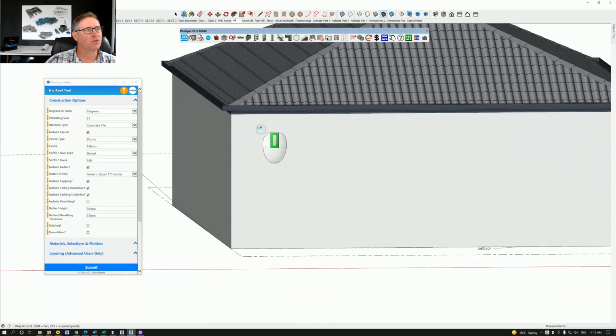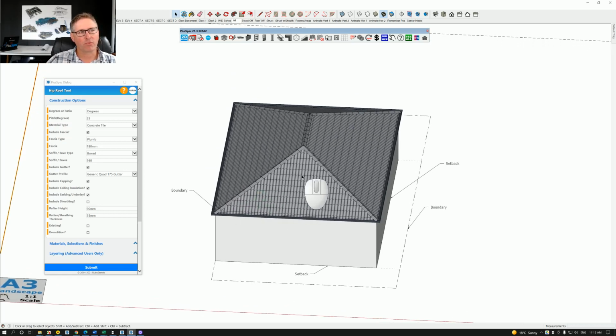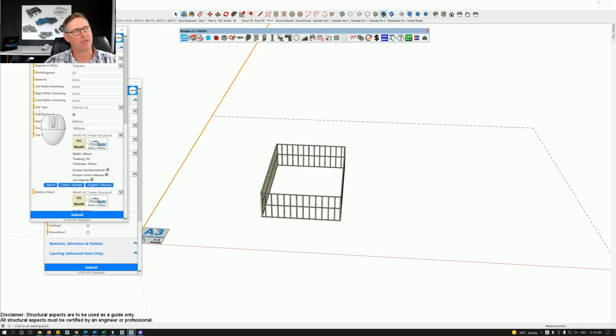And you can see I could have turned my gutters off if I wanted to. But most importantly, the roof is supported by structure, obviously. So let's have a look. Let's go to our structure scene here, and we'll put some trusses in, and we'll see if we can ascertain where the problem's going to come if we start pushing and pulling walls around later. Going back to why I think it's important to consider the end product at the start.